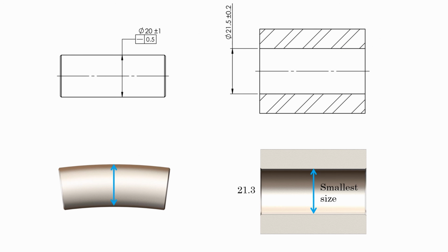So for the shaft at its MMC of 21 mm, the median line could be bent up to 0.5 mm, the defined maximum straightness deviation. This means the extreme outer boundary of the shaft could be 21 mm, the MMC of the shaft diameter, plus 0.5 mm straightness deviation, 21.5 mm.